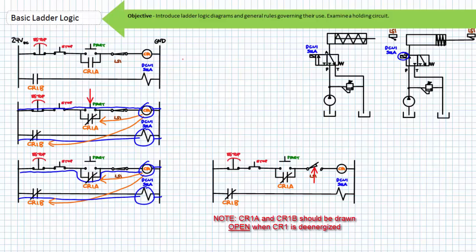The e-stop, in contrast, would be for dangerous situations, necessitating not only a stop mid-stroke and retraction, but also a complete disabling of the system until such time the e-stop is reset. Let's walk through the ladder logic together and illustrate the function of this one-cycle reciprocation system.